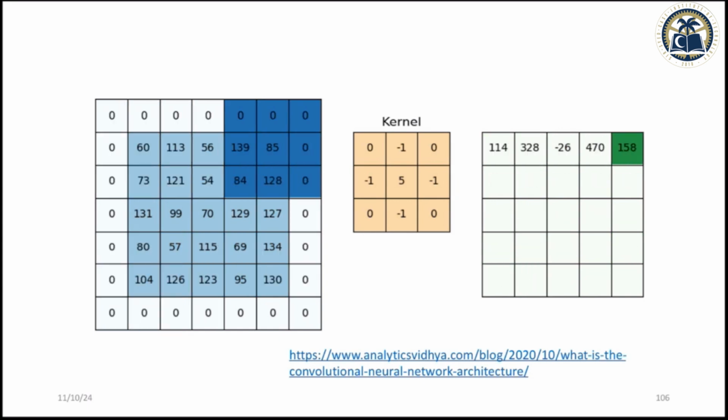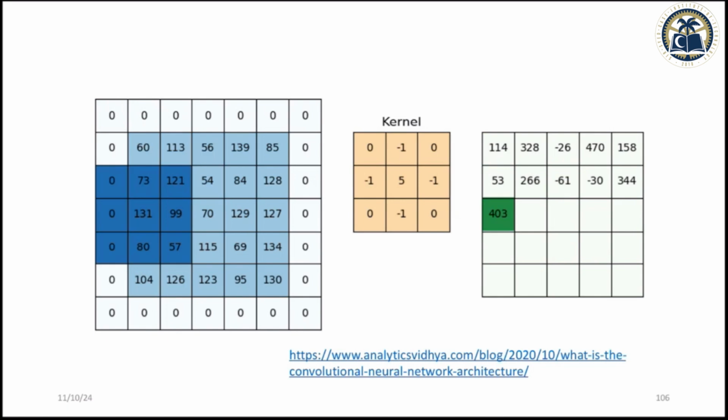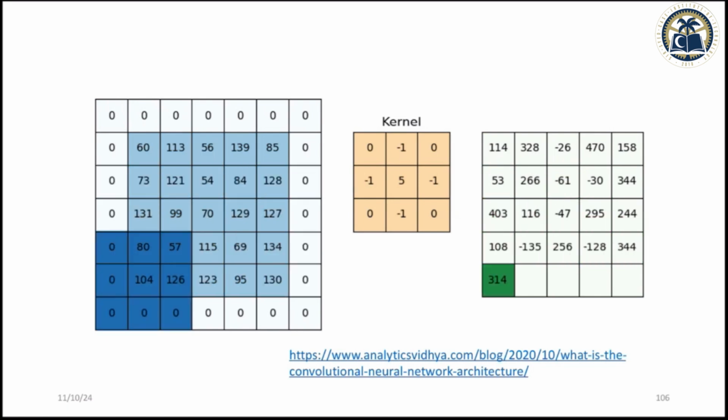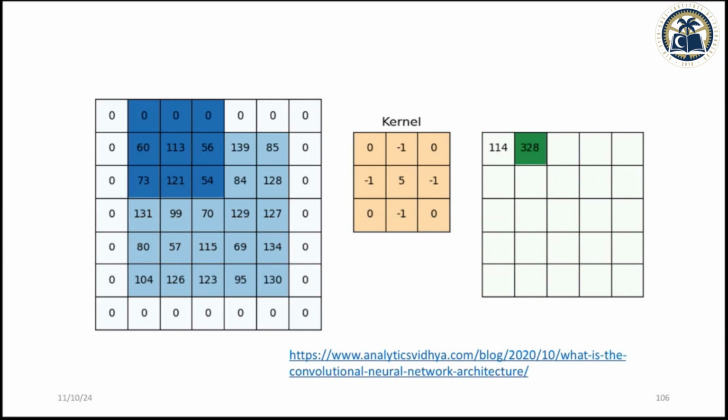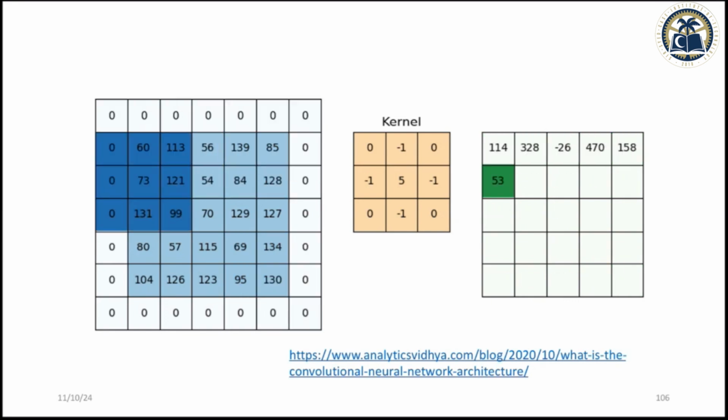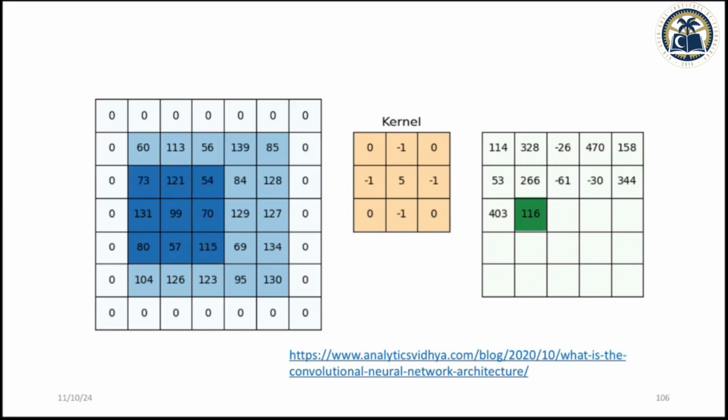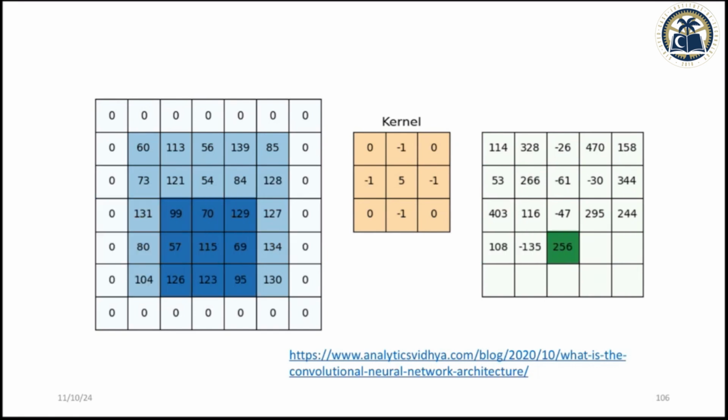I have all these registers and I just unroll all the loops. It's just unrolling all the loops and giving it to Verilog. How many multiplications are you going to require? You can figure this out. For every step, you need 9 multiplications, 8 additions.